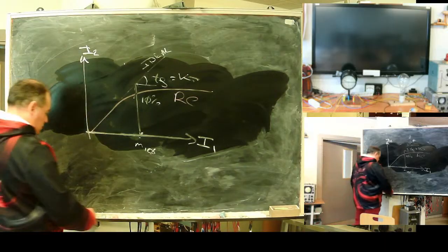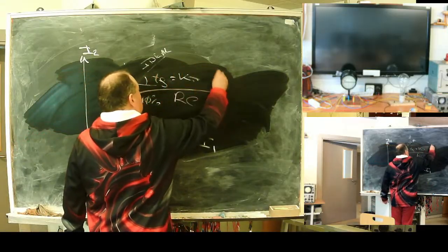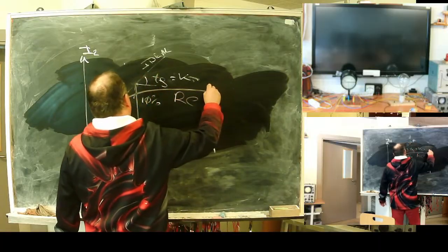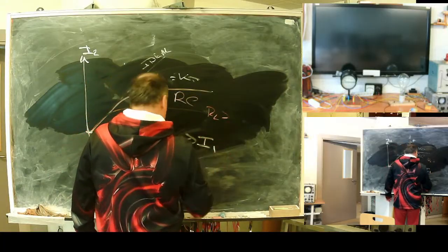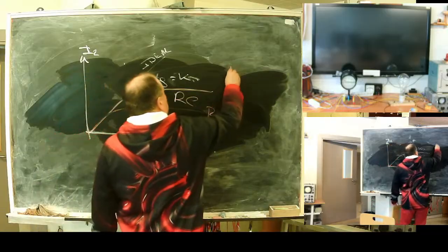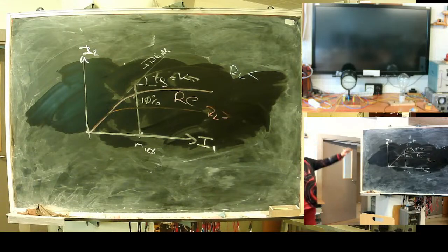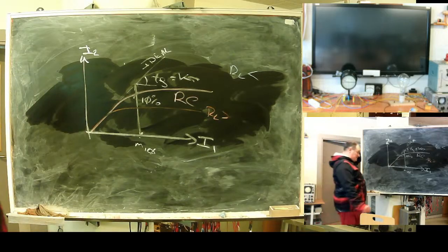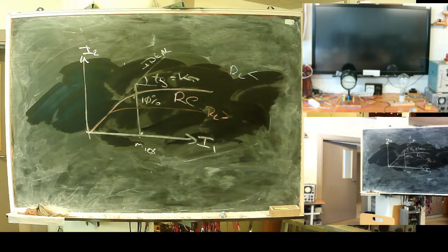The higher the load resistance, if you increase load resistance, you will get this one a lot higher, this one a lot lower. So the lower the load resistance, the longer the linear part will be, the higher the knee point will move. But there is one tricky moment. If you want to design such a circuit, you will need to find a balance.